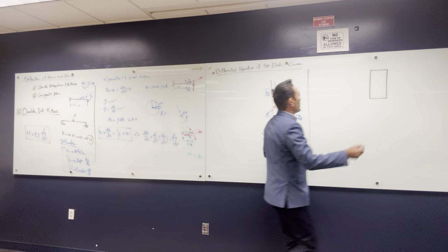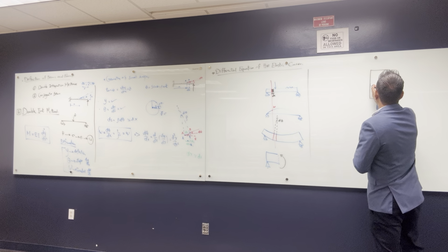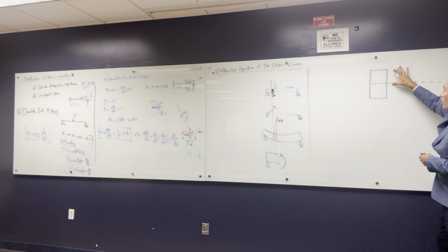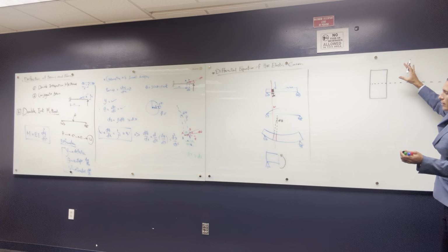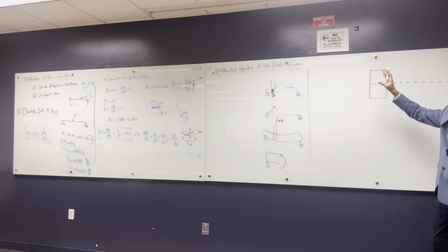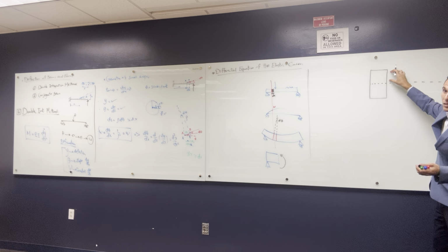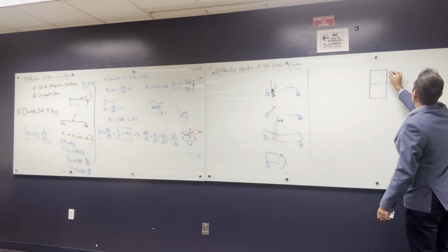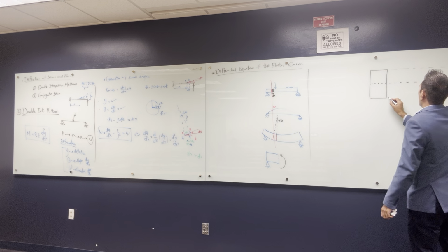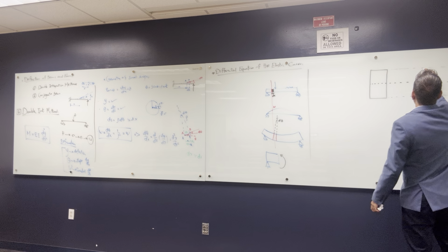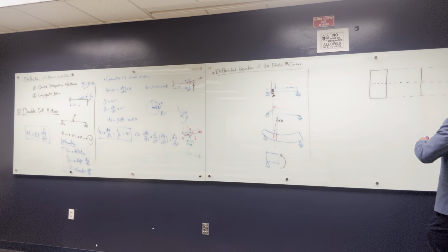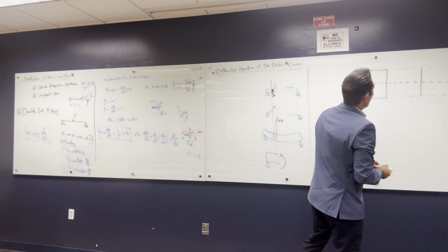All right, so let's get in the middle here. Assuming that the top part is going to have compression, like half of the beam, though it's not necessarily half, maybe just a little bit, it depends on how the moment looks, but I'm going to assume it's something like this. I want to draw the stress and the strain, how it's going to look. So I'm going to make a line that shows how the stress and strain look.